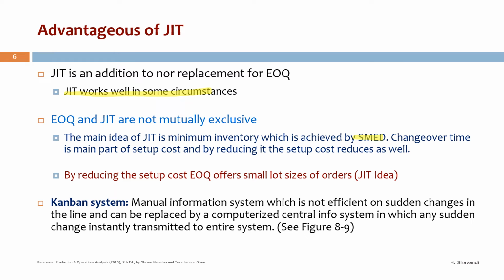But let's see how just-in-time works. Just-in-time relies mainly on SMED, because of reducing the time of exchanging the dies. When we reduce that time, we are reducing the setup time, and by reducing the setup time, we are reducing the setup cost as well. If we reduce the setup cost, the K in the numerator of the EOQ model, then the value of EOQ decreases as well.